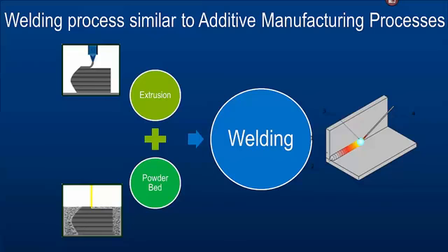In fact, a few of our customers started modeling at the manufacturing processes using the Abaqus Welding Interface and capabilities, the solver capabilities in Abaqus. But soon they stumbled upon bottlenecks and deficiencies and approached us for help. And with that then triggered multiple development activities. So last year, our R&D put in a number of resources and capabilities in the code to develop technologies for modeling AM processes. So methods were developed for AM processes like FDM, powder bed laser method, and so on. So for the modeling of welding process, we just took parts of both the workflow and were able to create the welding workflow. Once the workflow was developed, the AWI was rewritten from scratch as the second generation new and improved AWI, which we now refer to as AWI Pro.